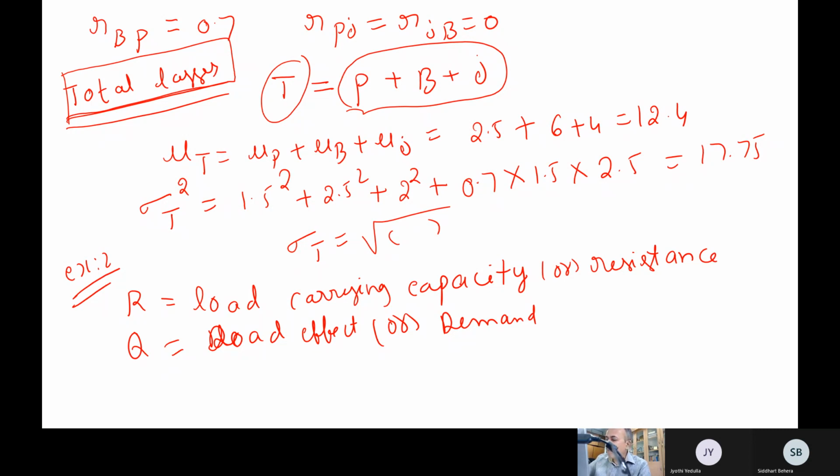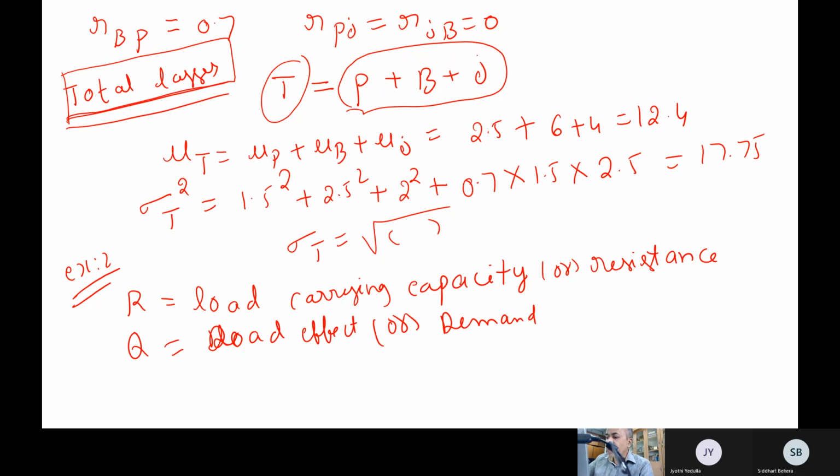So now generally we define the performance function. Okay, so what do you mean by performance function? In our structural engineering we have load and we have the resistance. How do we calculate the performance? So if I denote it by Y, how do you find out safety and other things? When your structure is safe, you have the load and you have the resistance actual. So what is your criteria? Now what will be the performance function? Resistance should be greater than load. That should be obvious.